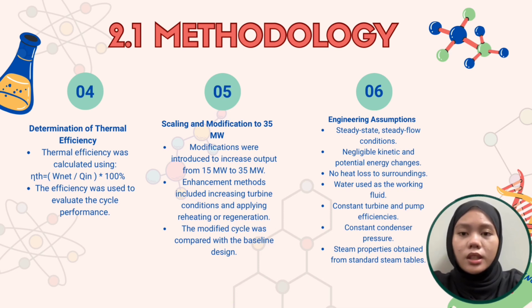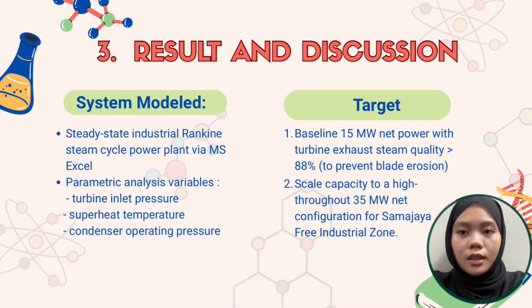Last is engineering assumptions: steady state, steady flow condition, negligible kinetic and potential energy changes, no heat loss to surroundings, water used as the working fluid, constant turbine and pump efficiency, constant condenser pressure, and lastly, steam properties obtained from standard steam tables.